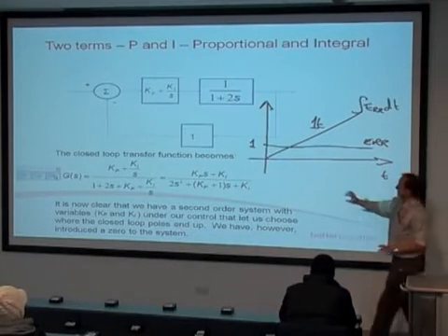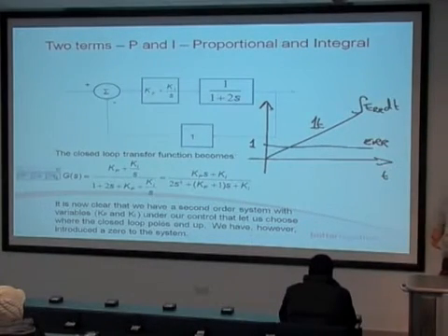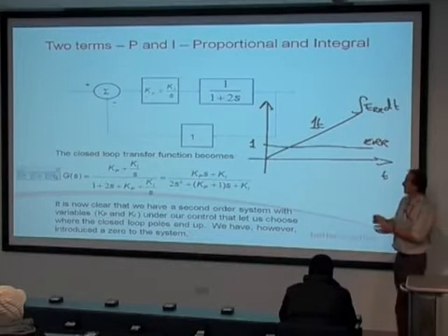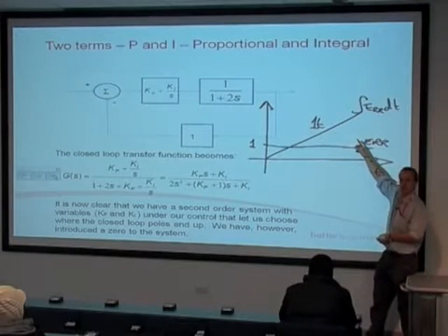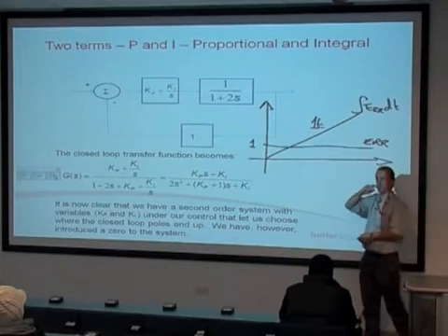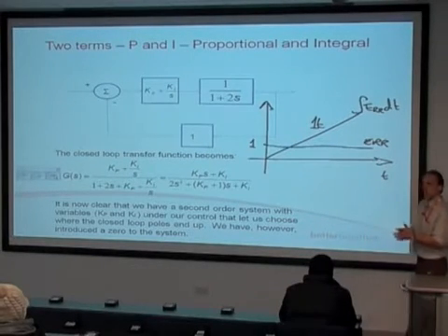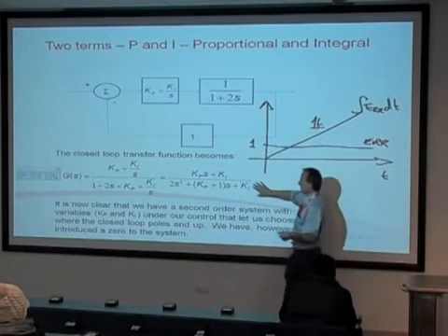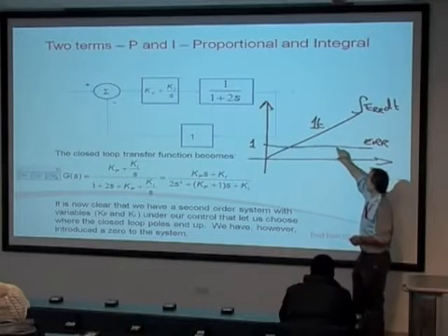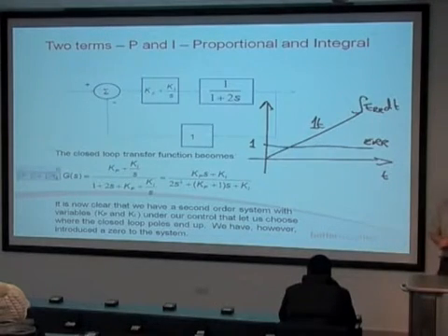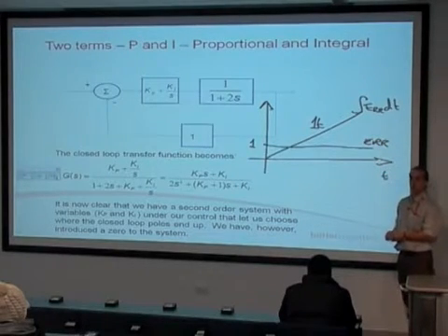So you can see what happens is if I've got a steady state error, a persistent error, what the integrator term does is say, well, that's not gone away yet. I'm going to push harder and harder to try and make it go away. So the way that we use the integrator term, as well as the nice theory about moving pole positions, you can also contemplate it as being a way to get rid of steady state errors. Because the longer the error persists, the bigger the controller output will be.